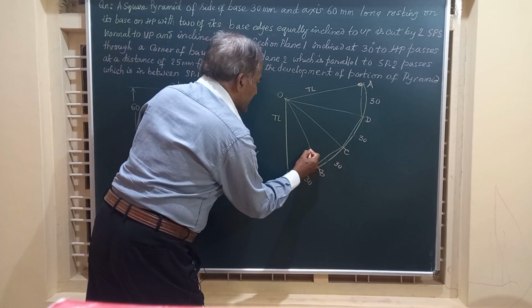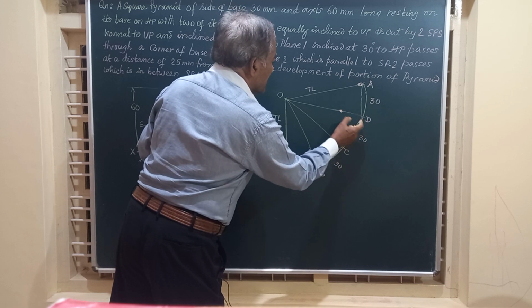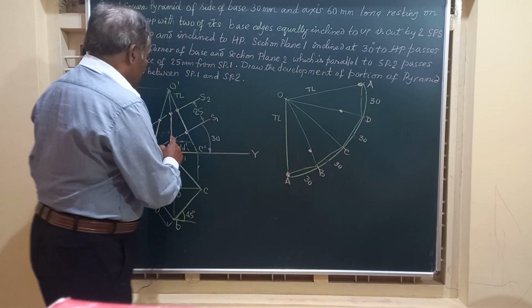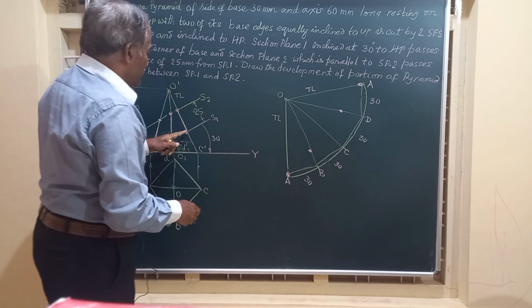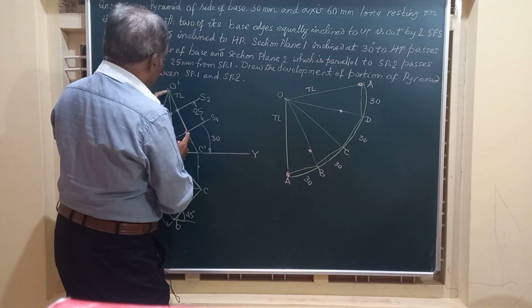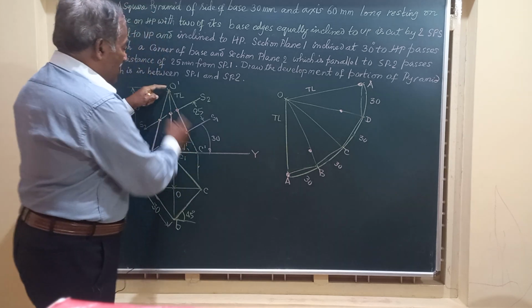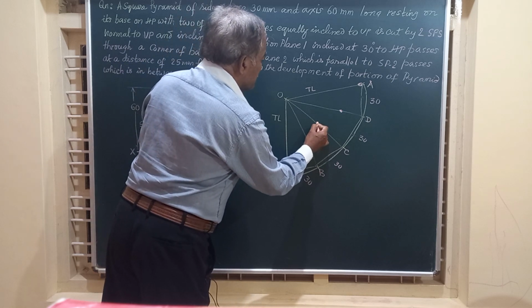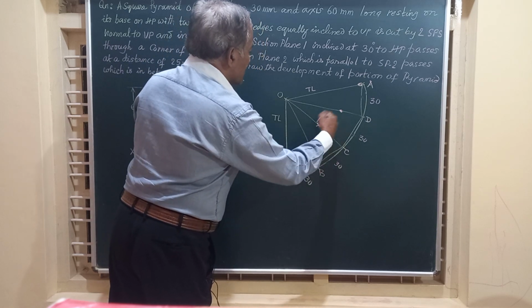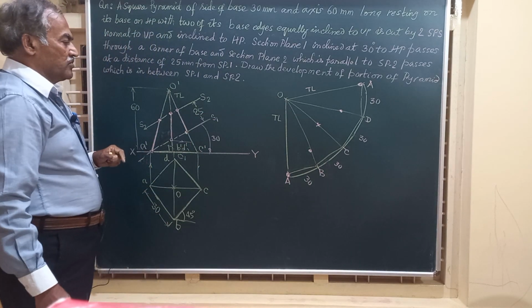On OB I will take this, and on OD I will take this. These two measurements are the same on OB, OD. It is cutting O dash C dash here, so I will take this measurement on this straight line because it's a true length. I will take on OC this length a little up. Friends, this is how the object is cut by section plane 1 1.